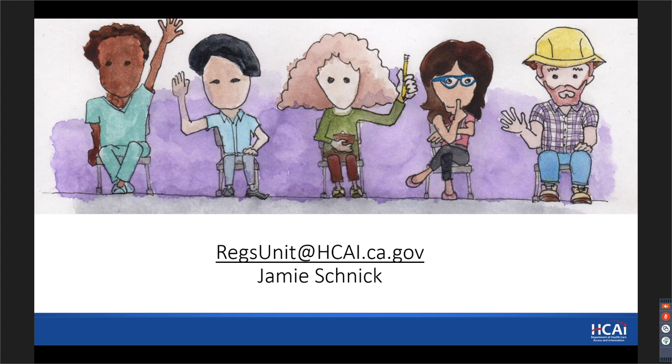Thank you, Jamie. Those are good questions. Next question is 517.31, marking of life safety and critical branch conductors. We'd assume this includes underground feeders and also assume the 20 feet interval will not be required of conductors in raceway with no more than 20 feet between boxes. Is this assumption correct?